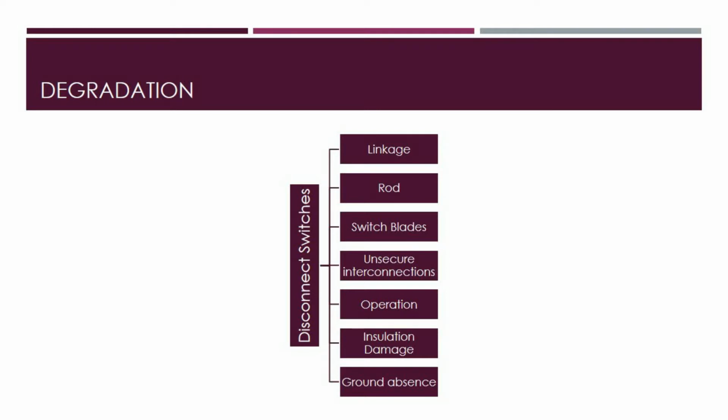Now, the switch blades and working mechanisms are the most important parts of the disconnect switch. Excessive arcing during switch opening or closing can be caused by misaligned or improperly surfaced contacts, leading to increased blade deterioration. Corrosion can cause the links and pins in the operating mechanism to corrode, slowing down the blade movement. Other flaws that may occur with age include broken grounds or damaged insulators.